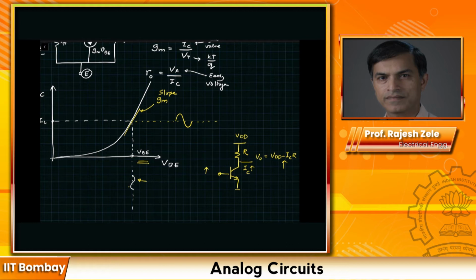When we say that there is an inversion from base to collector, this is the reason. When you're looking at the output voltage, then there is an inversion. But when you look at it from a voltage to current point of view, there is no inversion. Somebody can trick you in this particular question, and your fundamentals should be sound. So reiterating, from base to emitter small signal voltage to small signal current IC, there is no inversion. However, from base to emitter small signal voltage to the collector voltage, there is an inversion because of the VDD minus IC times R equation.